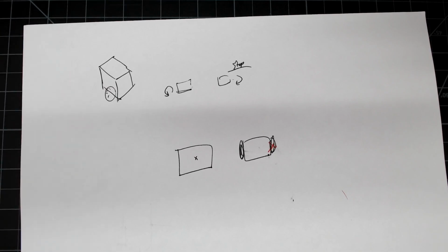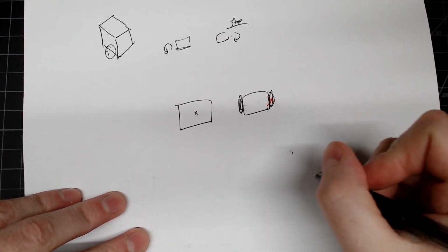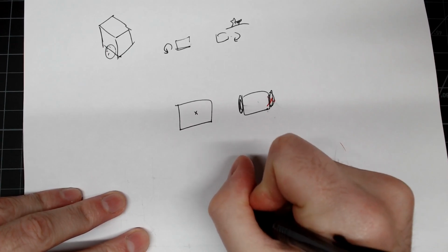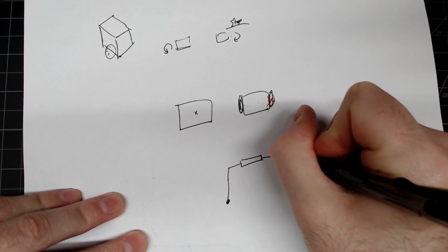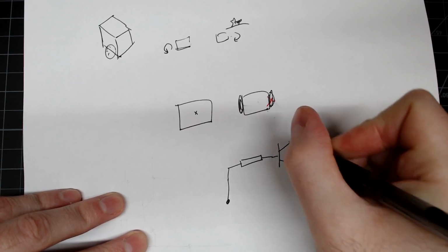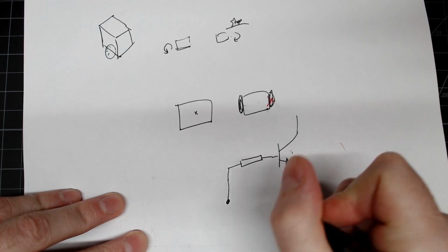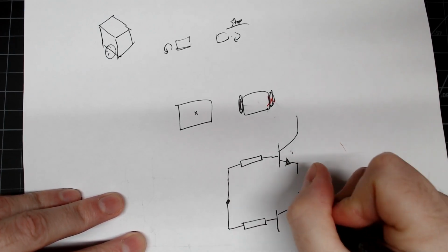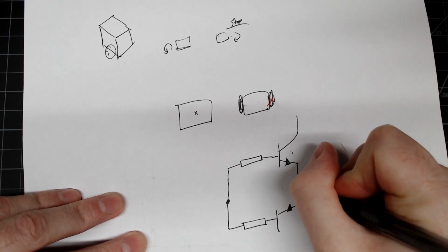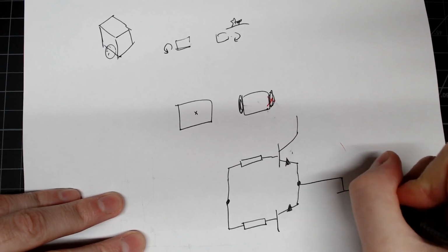The other option is they could actually give us two more, with just a couple of resistors and a couple of transistors. You can kind of do a forward reverse thing. The problem is that you'd have to have an actual positive and negative. So they could do something like this, let's see if I can draw this. You've got this point here, and you'd have to have this go into some transistor like that. This one is probably going to be your NPN. And then you've got another one that's coming on this side. You basically have a complementary circuit, but this one is PNP, so this goes the other way. And then these guys connect like this, and then this comes out to your motor.